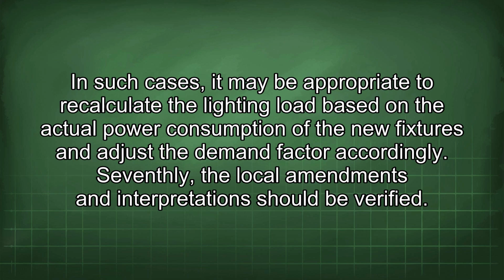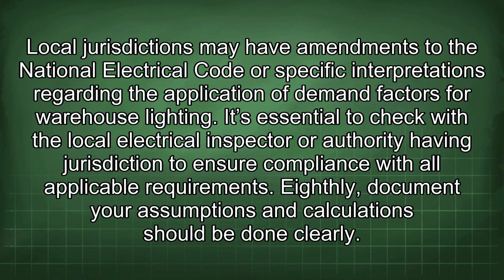Seventhly, the local amendments and interpretations should be verified. Local jurisdictions may have amendments to the National Electrical Code or specific interpretations regarding the application of demand factors for warehouse lighting. It's essential to check with the local electrical inspector or authority having jurisdiction to ensure compliance with all applicable requirements.